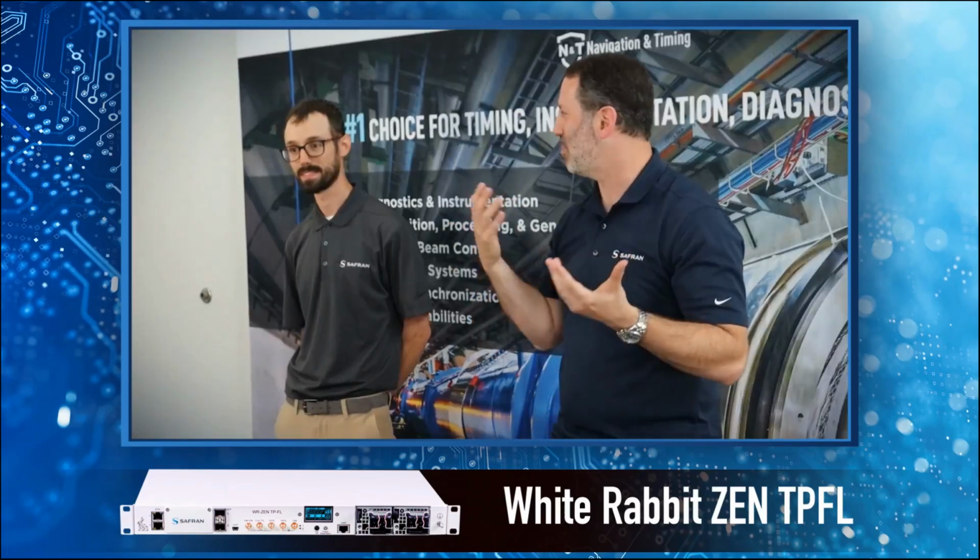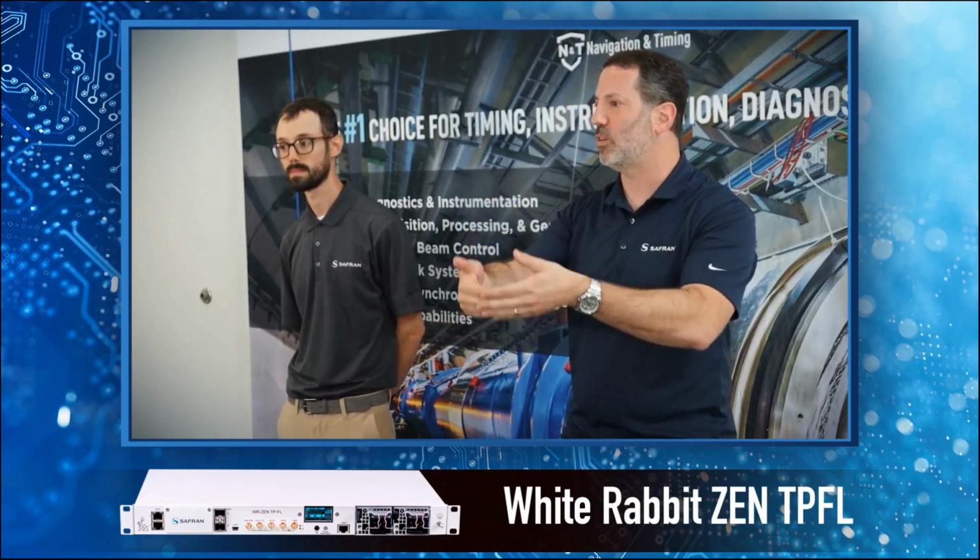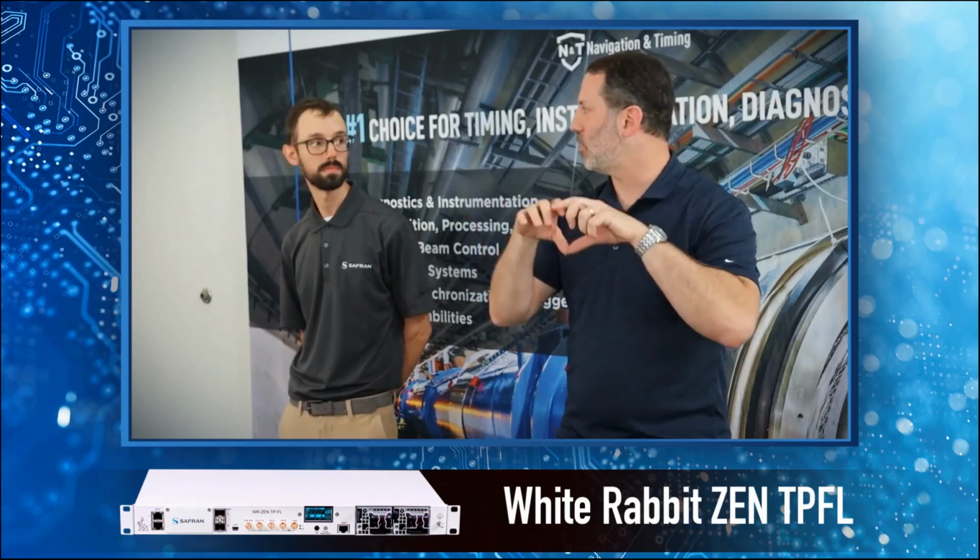The 1 PPS, 10 megahertz, IRIG, but also network signals like PTP, and that's for consumption by the end device. And so the TPFL sits there at that endpoint to do the conversion back from White Rabbit into the signals or other network timing that then will be consumed by the rest of the system.